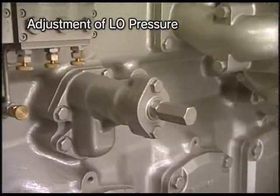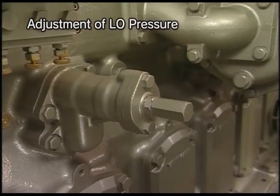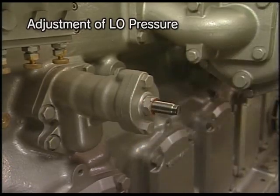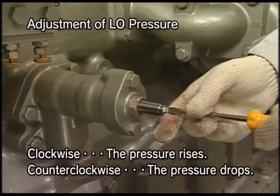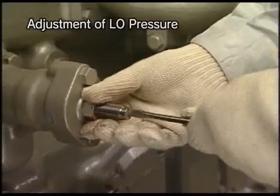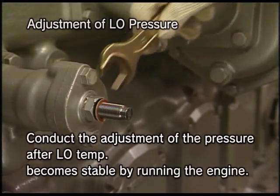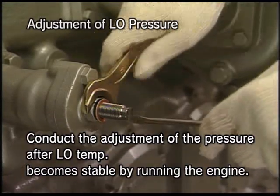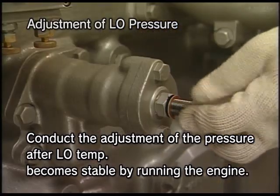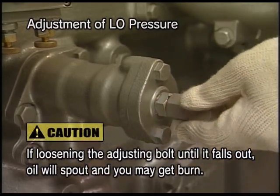First, I will explain the procedure for operating the adjusting valve of lube oil pressure. Remove the cap nut and loosen the lock nut. Make adjustments by screwing the adjusting bolt and adjust the pressure. After the adjustments, securely tighten the lock nut, screw the cap nut, and the work will be completed.